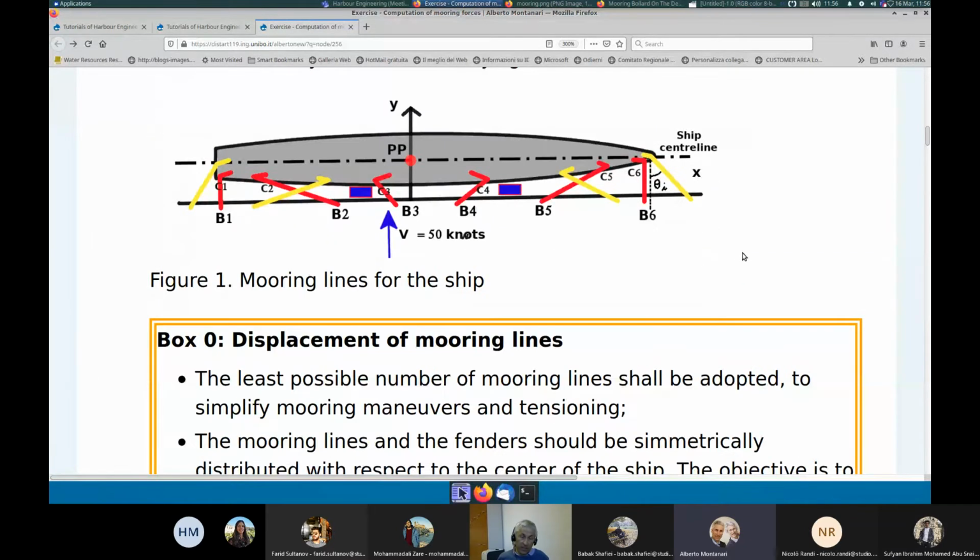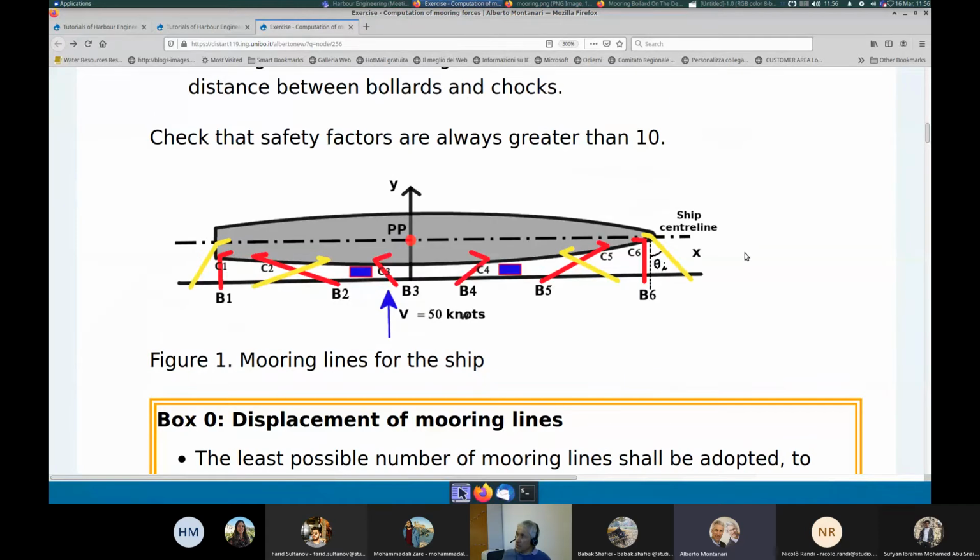Okay, perfect. And in general, keep in mind that safety factors in engineering are suggested by taking into account the possible consequences of a failure and the uncertainties. So if you have a large uncertainty, of course you need a larger safety factor. And if you have awful consequences, for instance when designing dams, you use a large safety factor. It's not enough to take, for a dam, 1.5 or 2. Usually a much larger safety factor is taken.